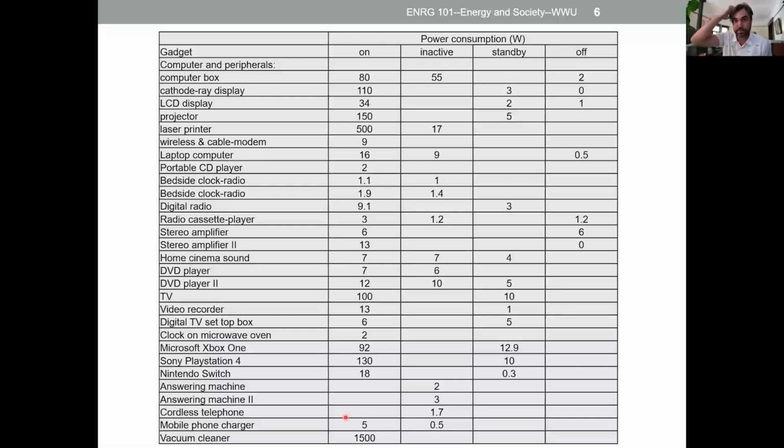Vacuum cleaners need to create a vacuum, which nature really doesn't like at all. You're creating this huge pressure differential. So you need a lot of power to do that. And so it's just going to pull as much power as possible to do that. And so it maxes out at about 1500 watts. So if you see something right at 1500 watts, it's usually making a vacuum or heating water. So, my espresso machine, that runs right at 1500 watts. Vacuum cleaner, 1500 watts. A shop vac, 1500 watts. Chop saw or whatever, 1500 watts. Okay, so that's where that 1500 number comes from.